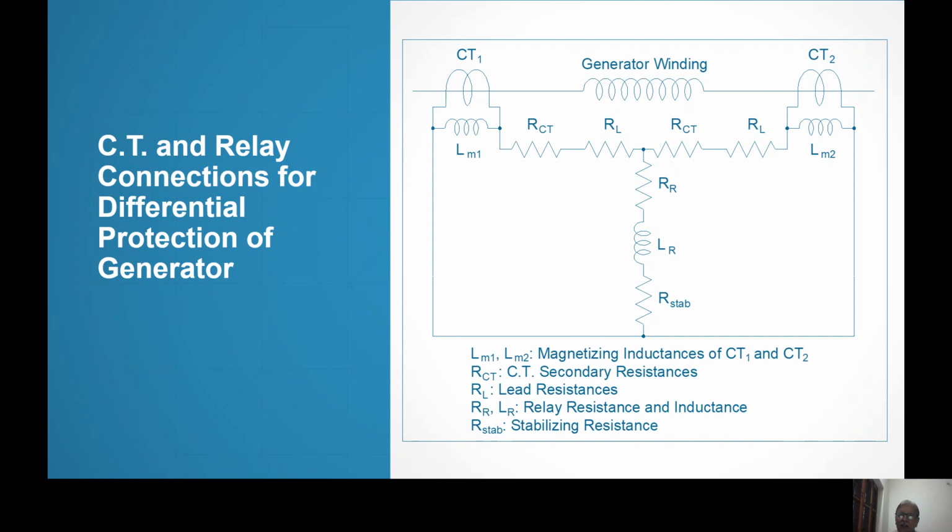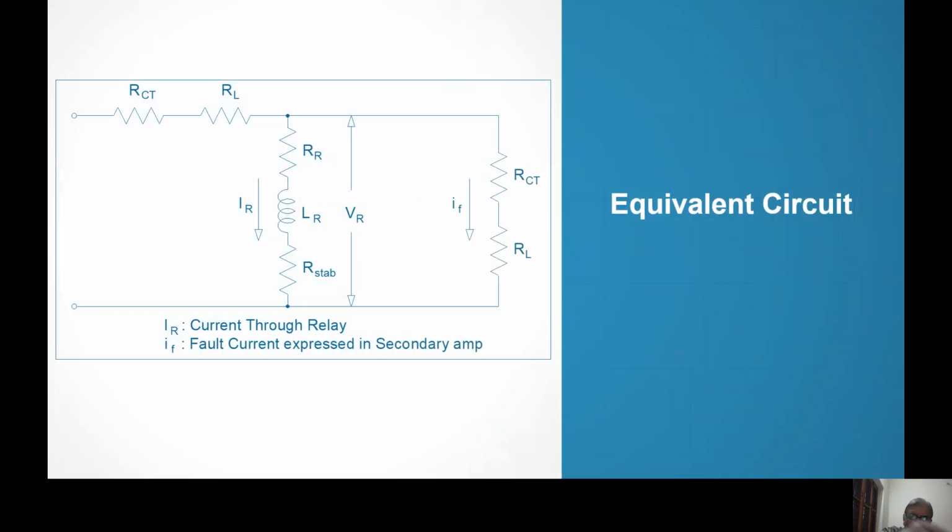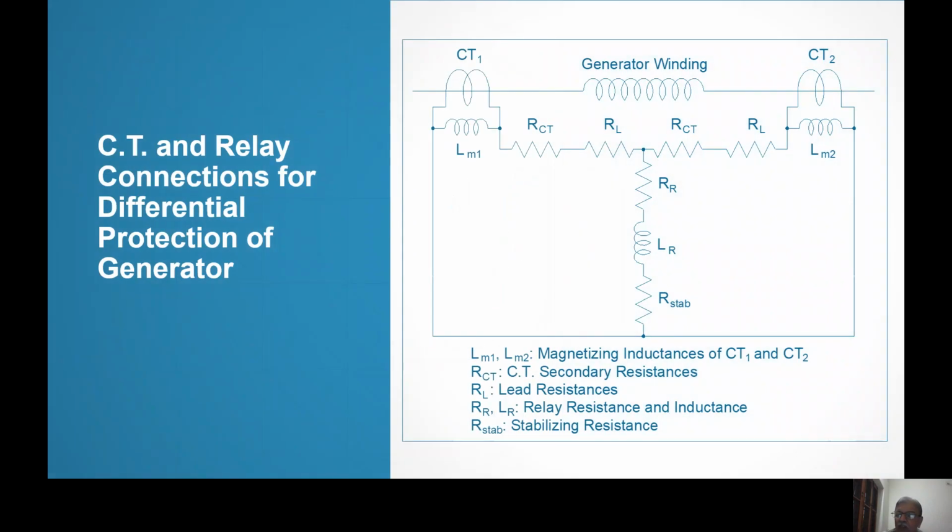Ideal means there is no shunt branch; it reproduces exactly. Not possible. This is just an assumption to calculate R step. So LM1 is infinite, which means it is open circuit. And LM2 is short circuit because it has gone to flat saturation, the worst condition.